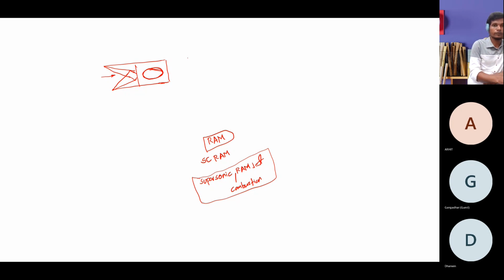I will give you one more hint to understand it clearly. If you have a flow separation like this, don't you see any streamlines that exist below this separation line? It is common to see a streamline starting from this point where you don't have any possibility to generate any kind of source or sink. Nothing is there because it is only a wall and fluid is not emerging, and you have a streamline here. That means velocity is passing from this point. So what does it indicate? It is also a kind of singularity, a source kind of singularity, but not a complete source, because it emerged from this point in the flow field, and the streamline starts intermittently.